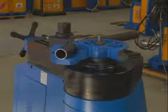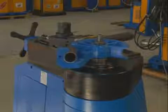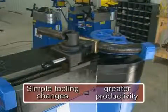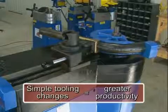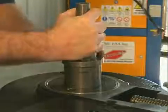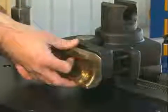For demonstration purposes, this video shows a 2 1/2 inch Schedule 40 pipe being bent to a 9-inch centerline radius. All Ercolina models offer simple retooling changeover, further increasing your productivity. Select and install the necessary tooling shaft. Slide the counterbending die into the dovetail on the vise assembly.